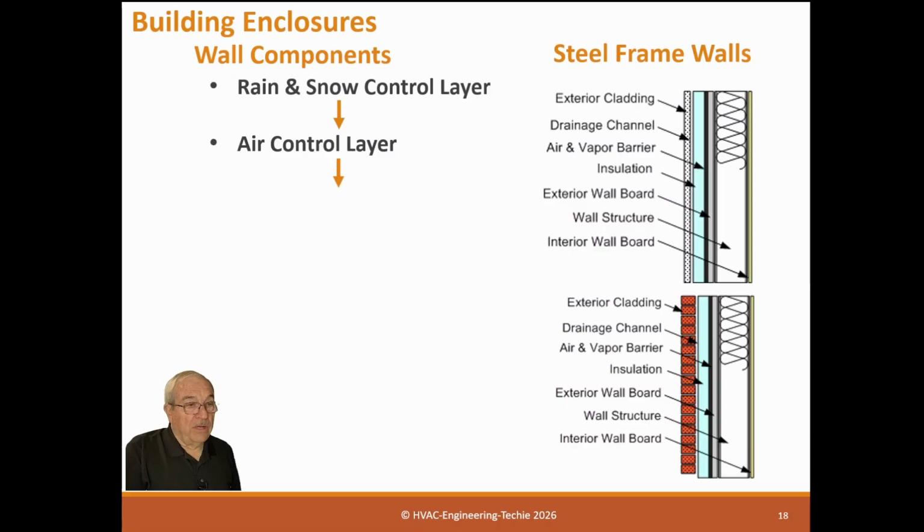So the holy grail is never, ever have two vapor barriers. If you have two vapor barriers, whatever's between them is trapped and can't get out. And that's where we have serious, serious mold problems. So you have to be on the lookout for that because some architects don't pay any attention to it. I don't know why. I don't understand that, but I'm dumb enough to say I can't see your vapor barrier. Where is it? And if they don't answer, which a lot of times they just don't answer, you understand they don't have any, so you have to pay attention to that.